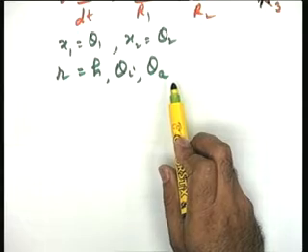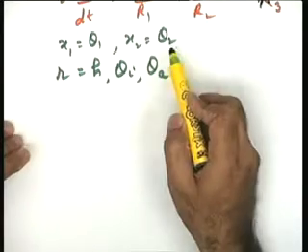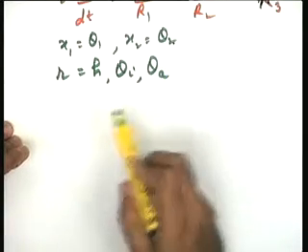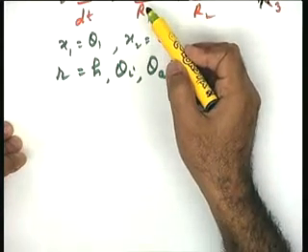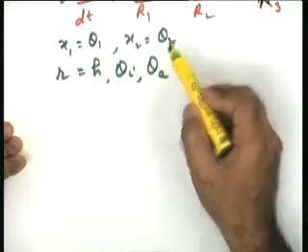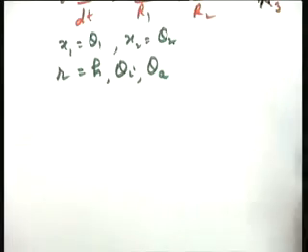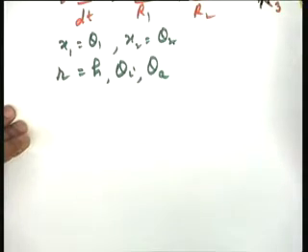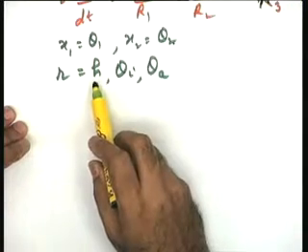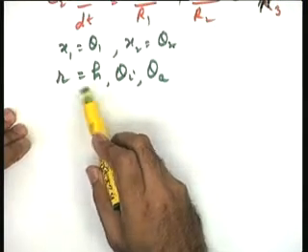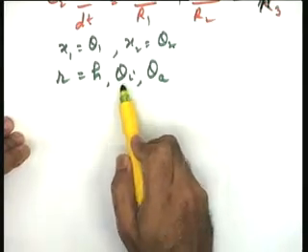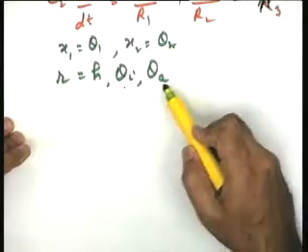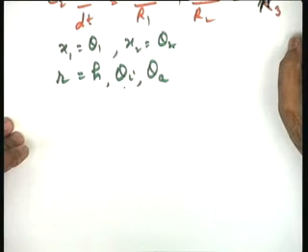You will have to take one output and one input. Taking theta 2 as the output, h as the input, theta I and theta a equal to 0, I will eliminate theta 1 and get a transfer function model between theta 2 and h. Identically, if you are interested to study from the input output model the effect of the disturbance variables, in that case the reference input or the controlled input will be assumed to be equal to 0, and you will set up a mathematical model between theta I and theta 2 or theta a and theta 2 as the study demands.